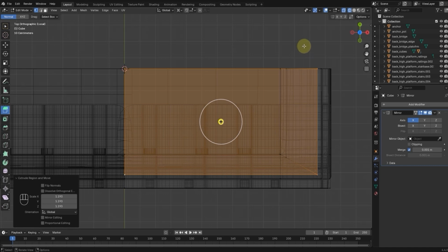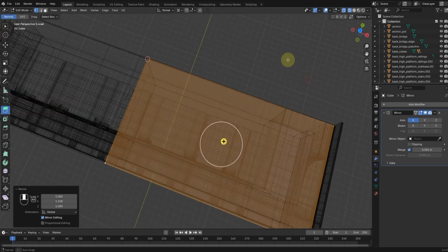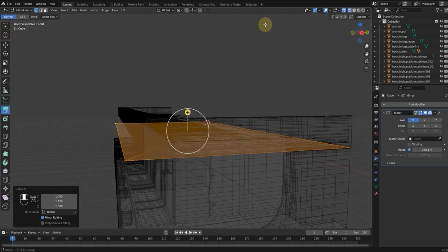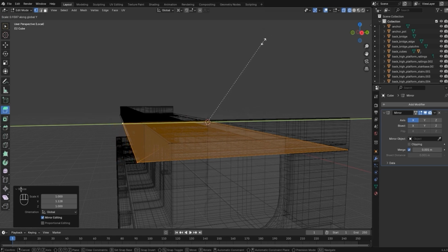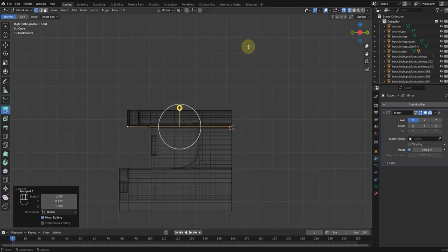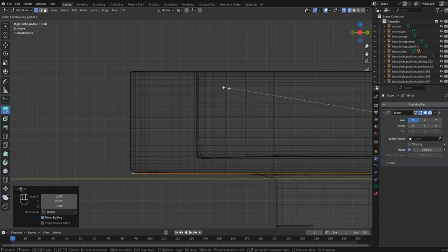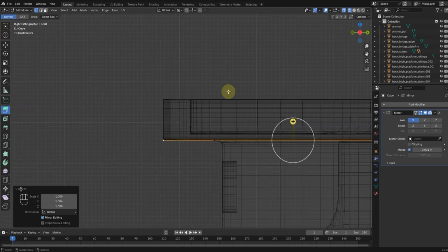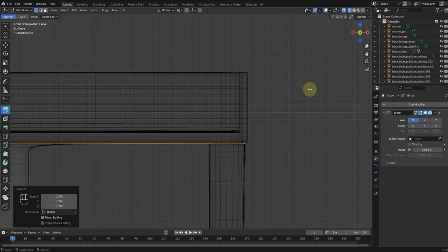So I'm going to now expand this to fill up the space for the main roof, and SX pulls across the X-axis. So I'm just going to bring it back a bit to come exactly. It was quite aligned with the balcony edge. So now I've made this accurate with the ends of the main roof. Press SX and it's going to drag it to there.